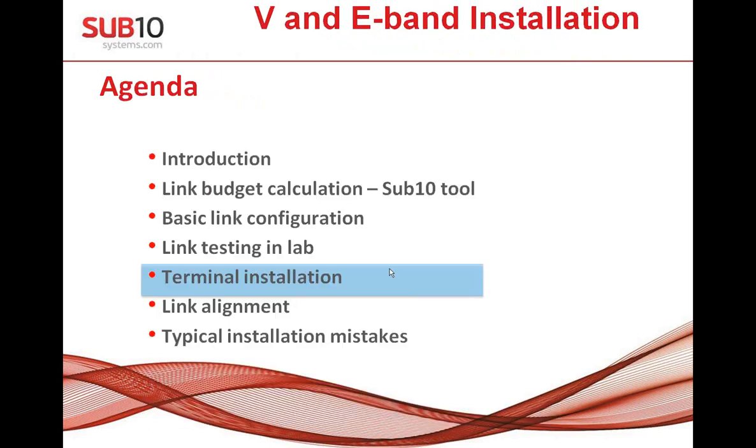Okay, this is about testing in the lab. Keep in mind you have to check whether the radio parameters and vector errors are okay, and the best way is to use ping to the opposite side when you are doing this movement, and you have to always wait some time: move a little bit, wait 5 seconds to see if ping is up or not.